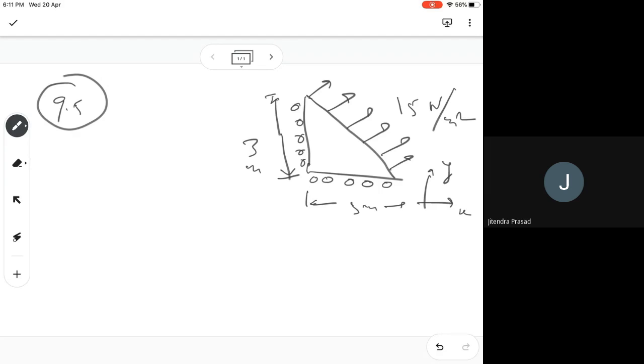So you have that, and what you are supposed to do is solve using one element triangle. So this is one element triangle. Boundary condition given. The boundary condition is constant. The AC is subject to traction normal to the S. So assuming Young's modulus E equal to 3 times 10 to power 11 Pascal, and the Poisson's ratio nu is given to be 0.3.